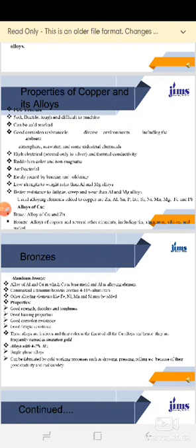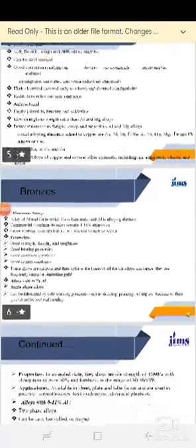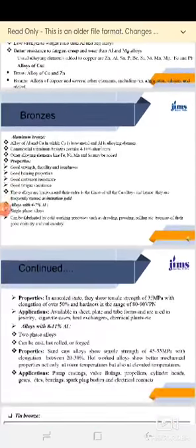These alloys are lustrous and their color is the finest of all copper alloys and hence they are frequently named as imitation gold. Okay. Alloy with 4 to 7% of aluminum, single phase alloy, can be fabricated by cold working processes such as drawing, pressing, rolling, etc. because of their good ductility and malleability.